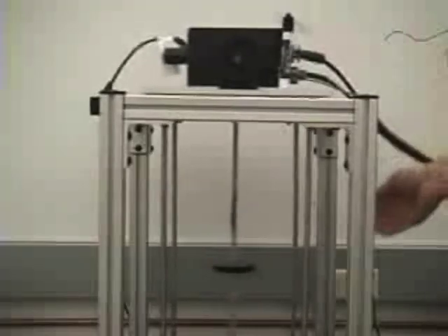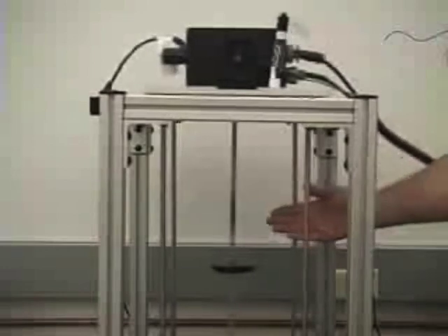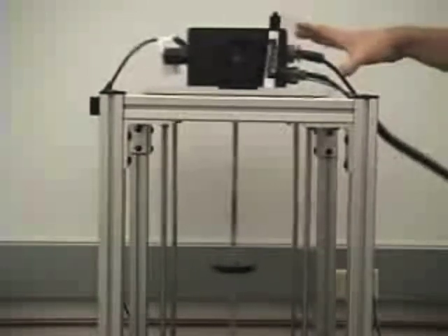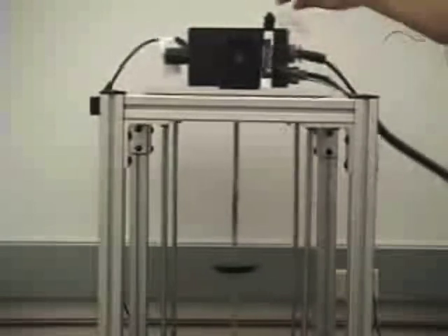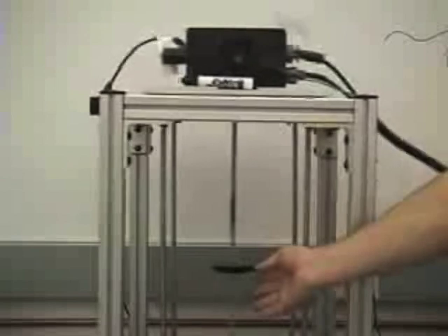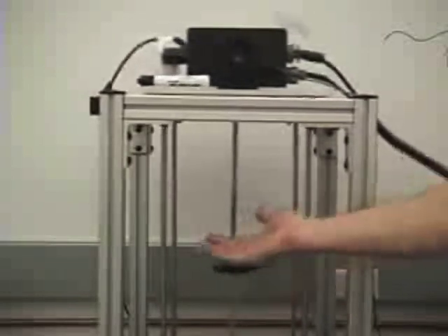Because at this frequency we're significantly lower than the resonance frequency of the spring mass system, it's essentially moving in phase with the larger mass, which is the imbalanced mass moving at the force function. In this case, it's not doing anything to dampen the vibrations because we're so far below its resonance frequency. It's simply moving in phase with the imbalanced mass.